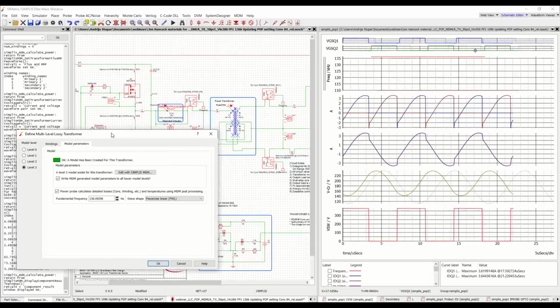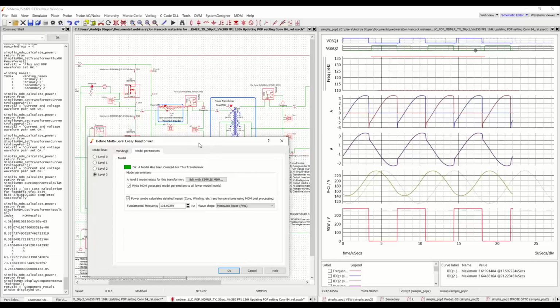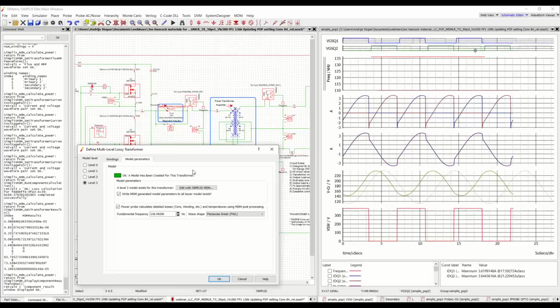Another issue here is the frequency. Here in the LLC, our switching frequency, or our fundamental frequency of the magnetics waveforms, is changing as we change both the input voltage, the output load, and as we change the design. And we change things like the magnetizing inductance and the resonant inductance and the ESR just of those two components. So it's important to have that number correct.